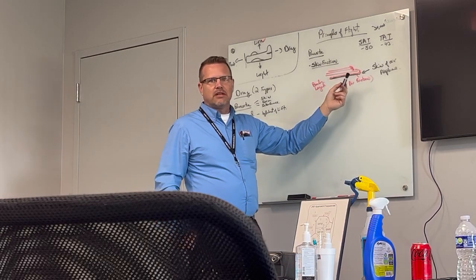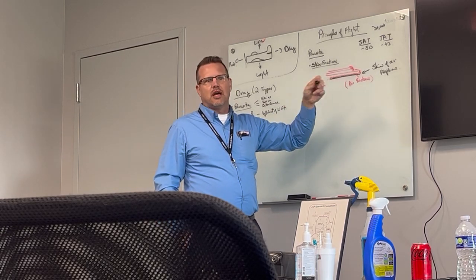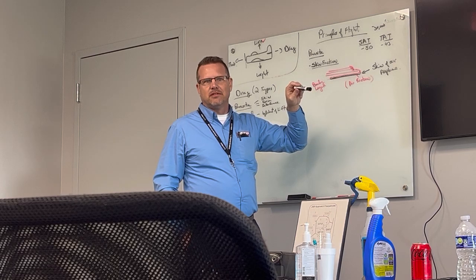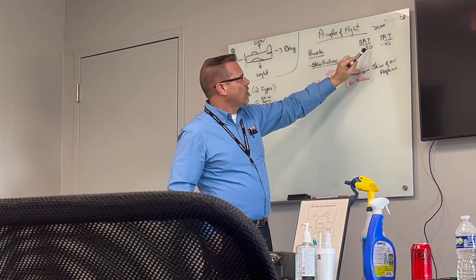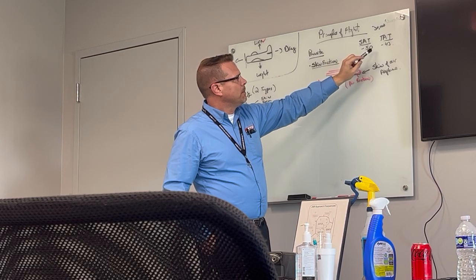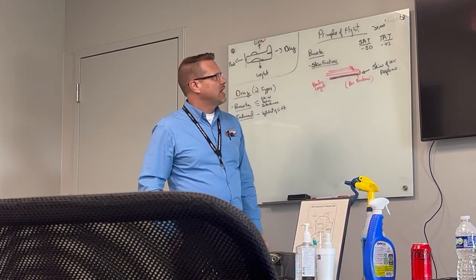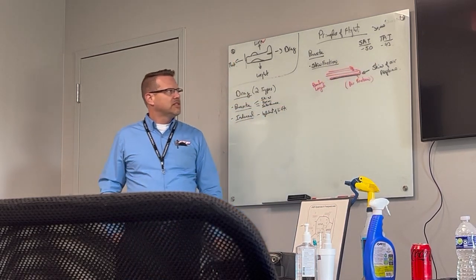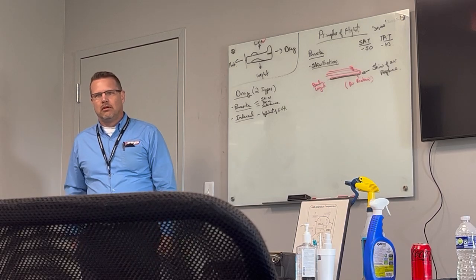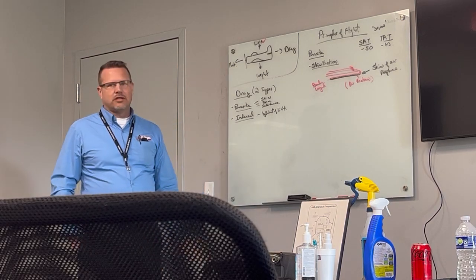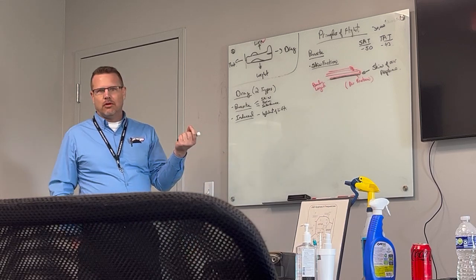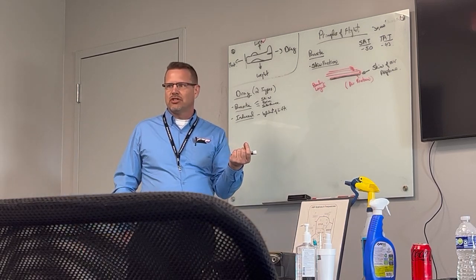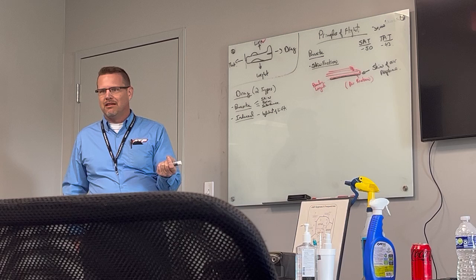So at about 32,000 feet, all times of the year, it's -50. We're very close there to it on a semi-standard day. So it's always right around -50. But as we're going Mach 0.82, we have another temperature that's 8 degrees warmer. And that's our total air temperature. They have a probe on the plane that actually measures the temperature of the skin of the plane.